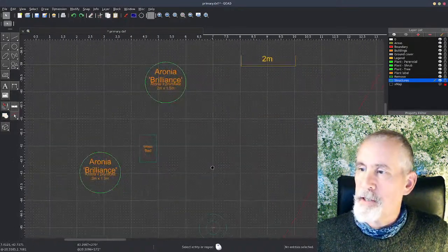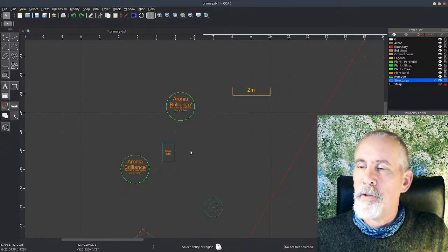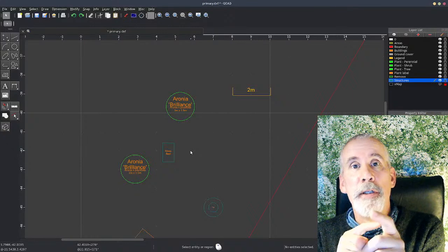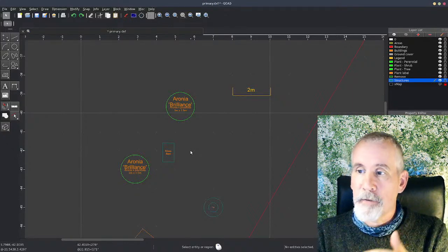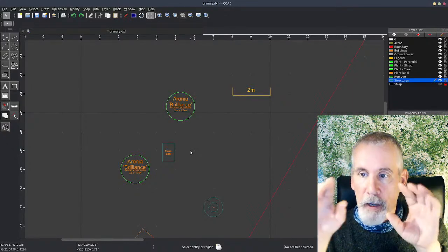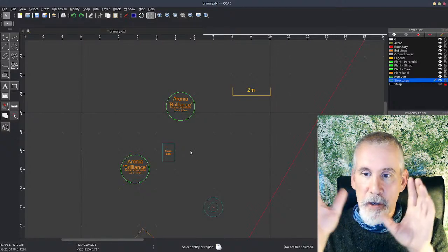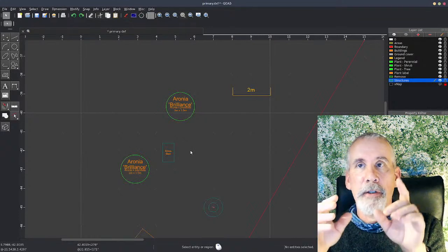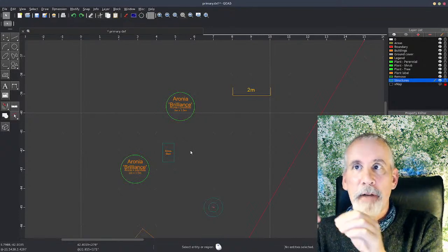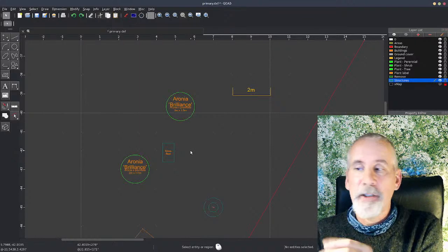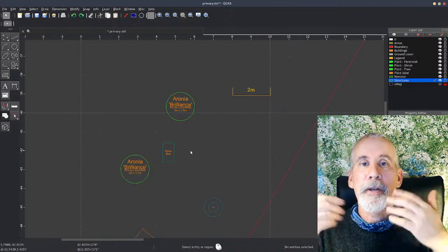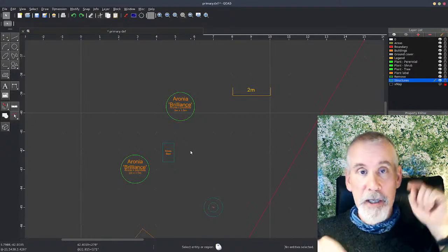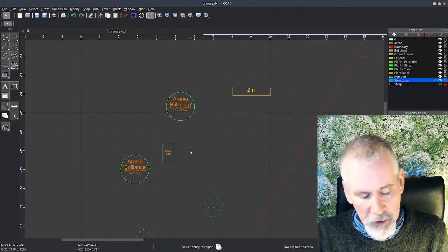The other really good thing is to create a block that you can then rotate and have in different positions. You create a block as you see it, but then by putting an angle on it, you can fine tune the angle. You don't have to create it perfectly right in the first place. So you've got a bench, which is what I'm going to create, and then you can tweak the angles on the block itself. It makes it a lot easier to use. I'll show you what I'm talking about.